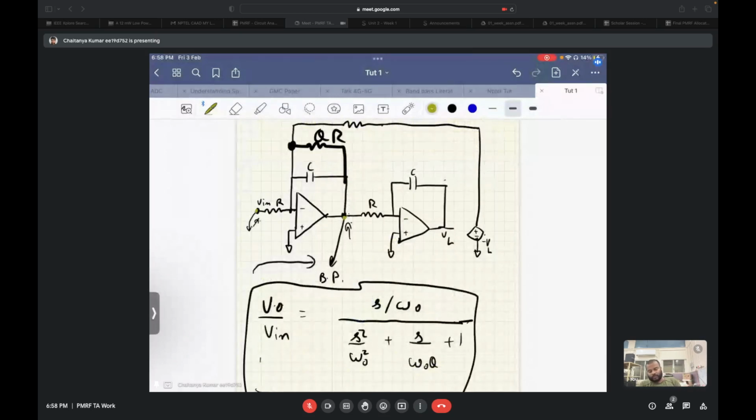So till now we have looked at a low pass architecture with the damping resistor at the second integrator and the output at the output of the second integrator, and a band pass structure where the damping resistor is at the first integrator I1 and the output is also at the output of the first integrator.